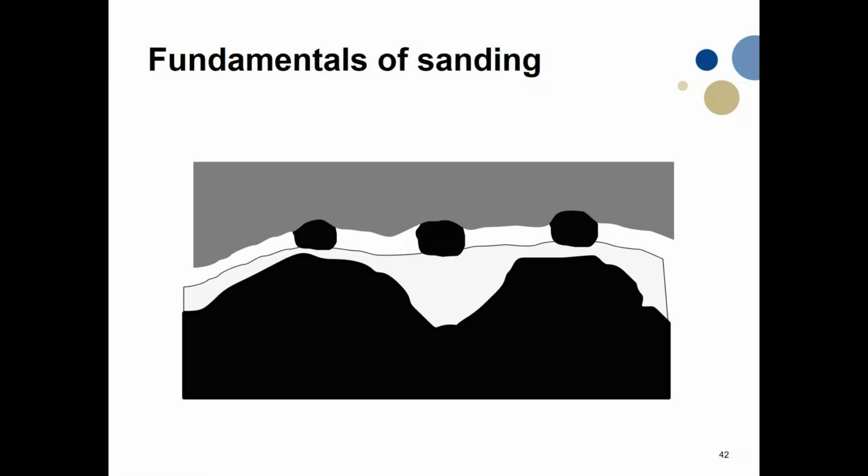So typically high speed, above 60, 70, 80, or 100 kilometers an hour, is typically not very useful for sanding and gritting. Then you typically tend to go to this bare road strategy. But on rural roads and in colder climates, it is still a useful way, and maybe actually a better way, to maintain your road surfaces.